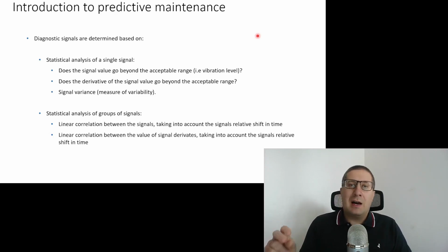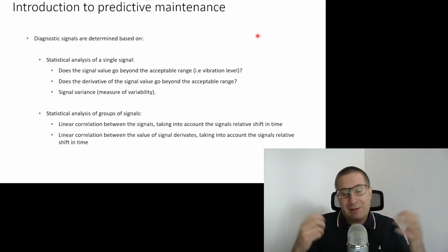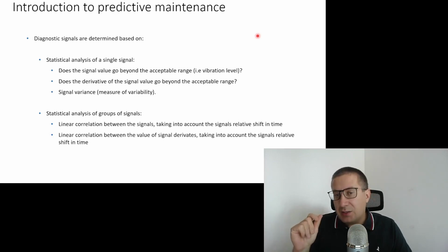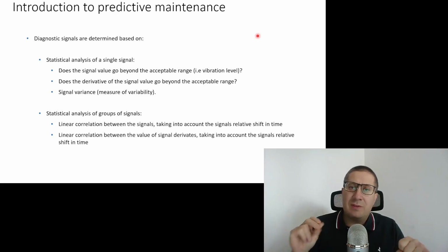Usually the alarm module in distributed control systems operates based on the comparison of the process value and some ranges. If the value is beyond the acceptable range, then the alarm is raised. But of course, this is a very simple approach. We would like to detect some slight difference in process behavior, very early symptoms of a failure. So probably such an approach would not be enough.